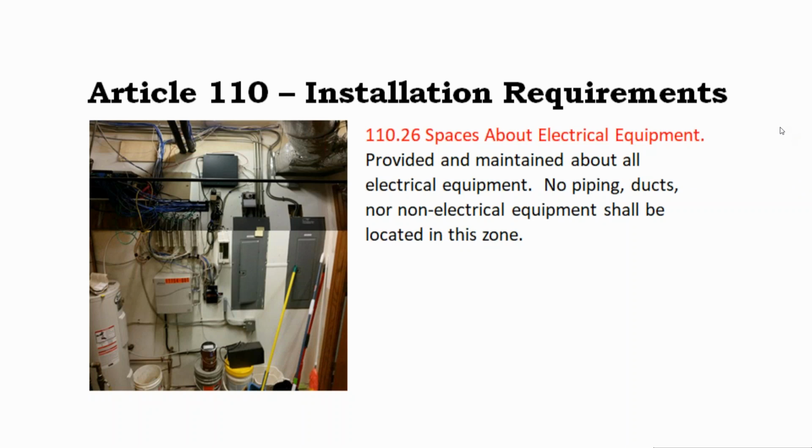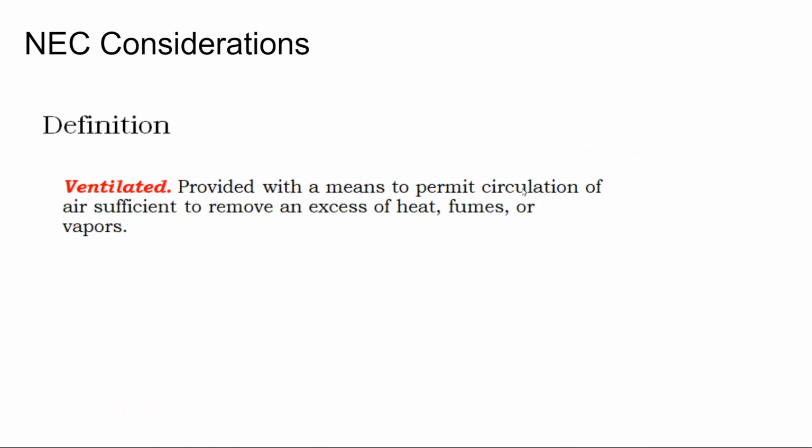And so the key point here is your space for your inverter and your space for your batteries has to be just electrical space. Often homes will have a closet for their tank water heater. Now you have to have a room for your battery equipment, electrical equipment, and it takes up more dedicated space than a tank water heater. Now, these spaces can be adjacent to each other. It's more like an invisible fence that you can't pass over.